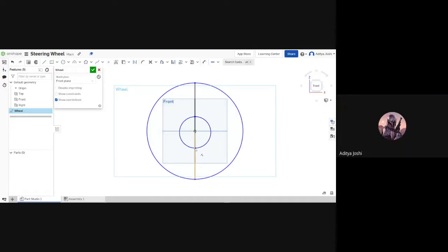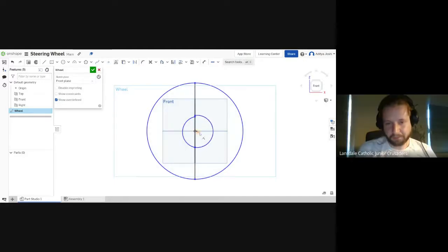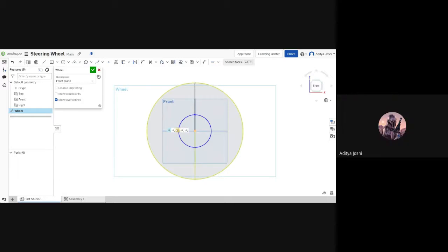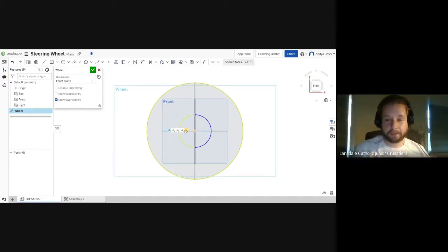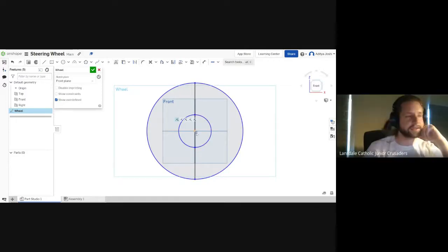I'm trying to, now it's combined. Yep. So when you moved it just like that, wait, stop there for a second. Do you see how when you click and drag something, like grab the center, you click and drag that and bring it towards the center? Do you see how that little coincident constraint shows up? That means that when you let go of the mouse key, it's going to add that constraint. Oh, okay. Does that make sense? Yeah. It's a little bit confusing for sure.